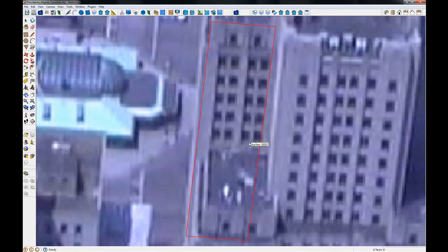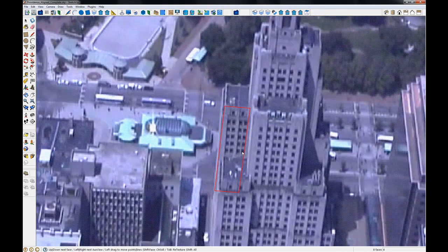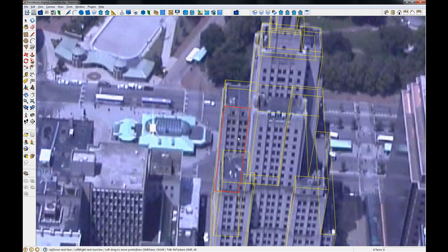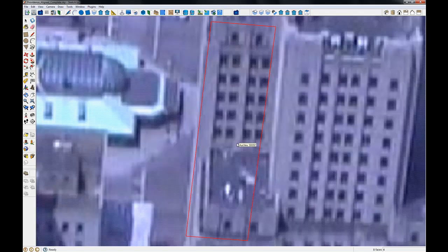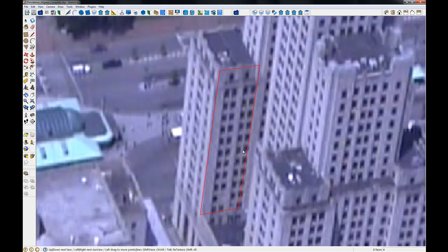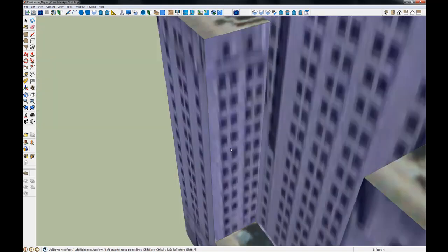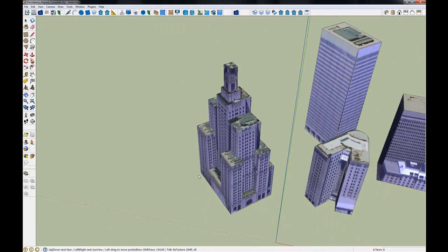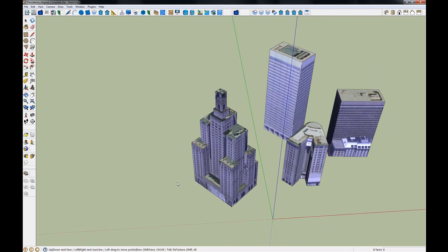Now use the up arrow again, and again you see that this face is that back wall. I'll hold the Alt key down to see the context, and I'll use the left arrow key to switch to a different aux view. Actually, I want to go to the right arrow, and now we can adjust that individual face, move it a little bit, move this edge over a little bit more, and hit the tab key and retexture that. So that way we can edit multiple textures at one time.